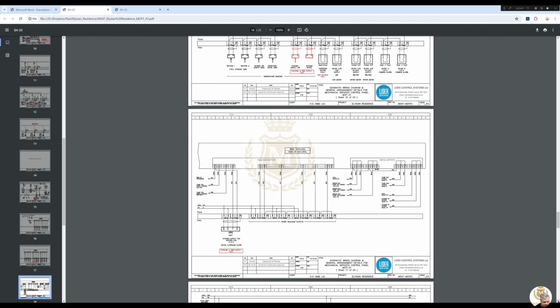And then we've got 1 analog output and 2 for speed, but one of them is for the kitchen supply fan heating coil. So that'll be using a thyristor, I should imagine. Spare analogs there, and then the digital outputs are there.